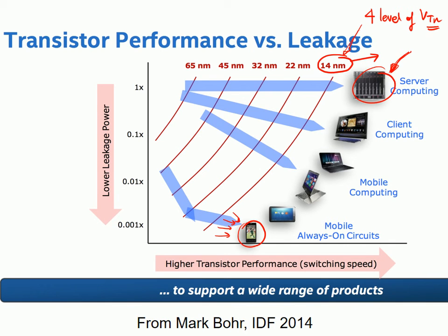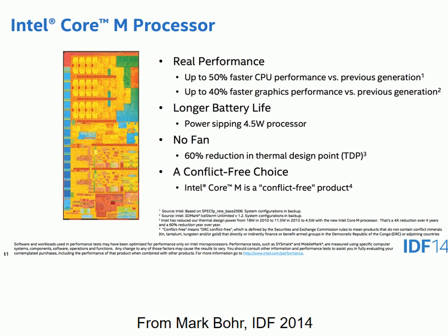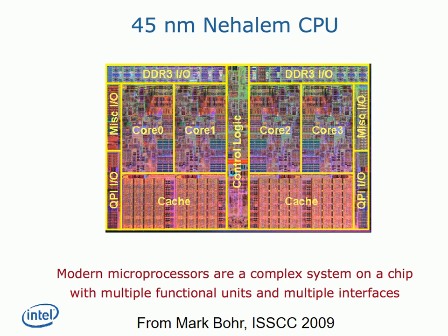The next technology, which is the 10 nanometer technology, will have 6 levels of threshold voltages, so that it's really increasing. You can use the same technology for very low power smartphone processors and for servers, just by using the different transistors that you have in the same technology. Okay, now I can stop here for discussing this issue.